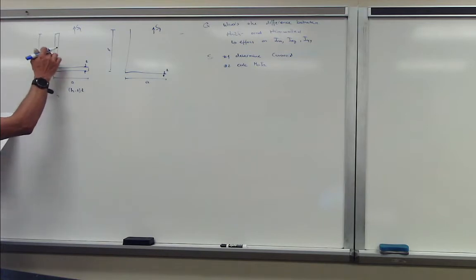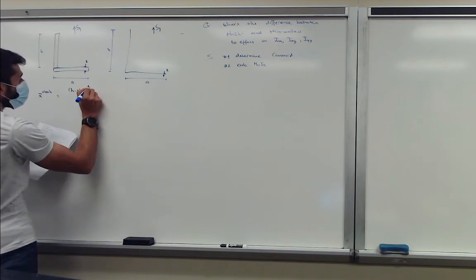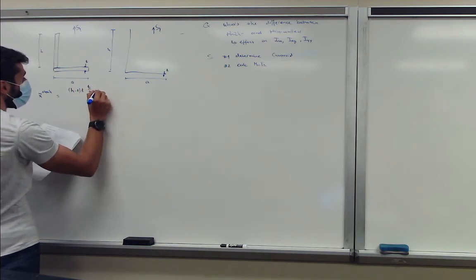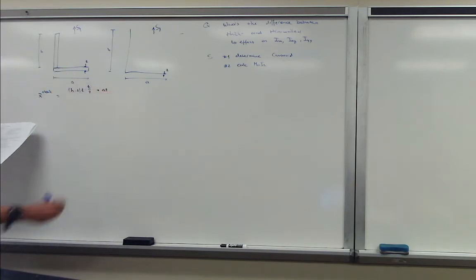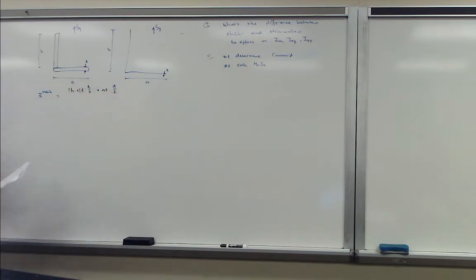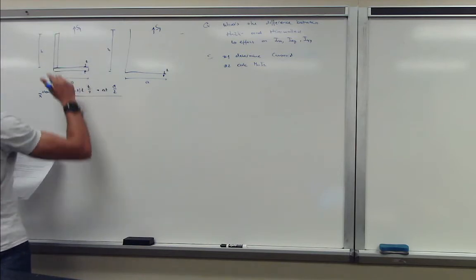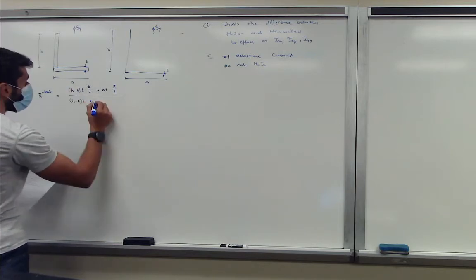Yeah, so with respect to the x-axis will be here in the middle. The thickness is t, so it's basically multiplied by t over 2. Plus this part is basically at, it's the area, and multiplied by a over 2. And that's the distance from its centroid towards our center point here, at least this left axis, where we calculate the x-axis from, okay? And we divide that by the total area, of course. And that's area from the first part was h minus t multiplied by t plus a times t.